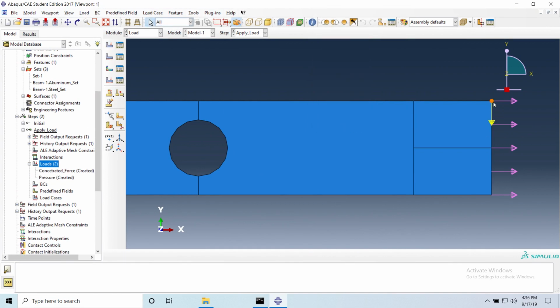at that particular location. You said that you created a surface when you applied the pressure? Yes. And is it the same if we don't? Yes. So the only thing with creating surfaces is that later, when you are requesting outputs, you can request an output for that surface only. Okay? But if you don't create a partition at that edge, could you just create a surface and that'd be the same thing? Or this partition here, yeah.